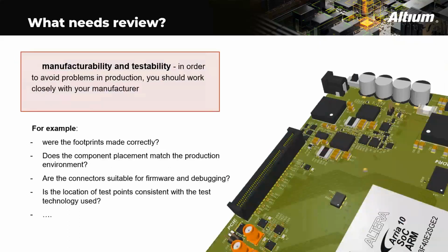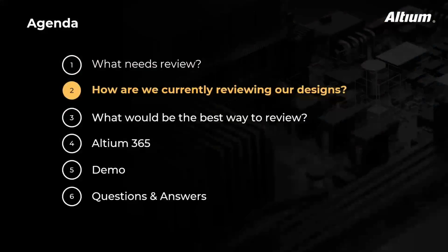Last but not least, manufacturability and testability. You should check if your footprints were made correctly. Does the component placement match the production environment? Are the connectors suitable for firmware and debugging? Is the location of test points consistent with the test technology used?